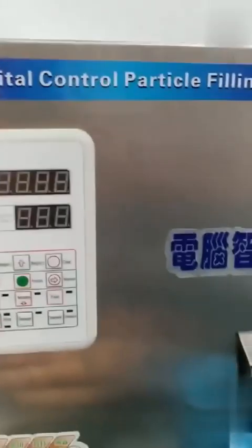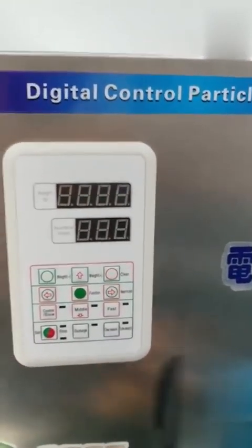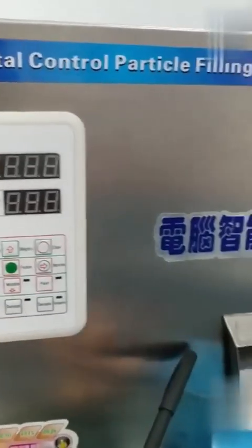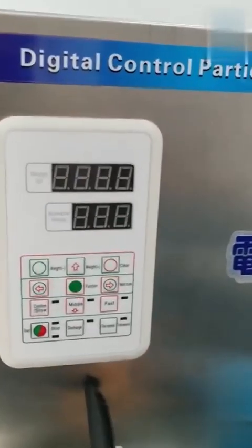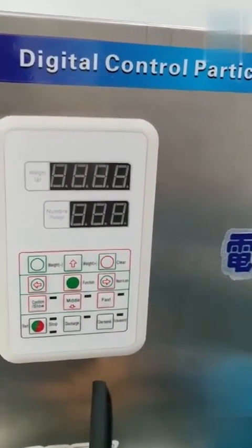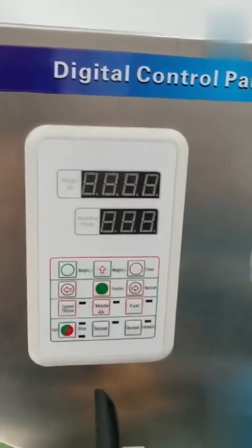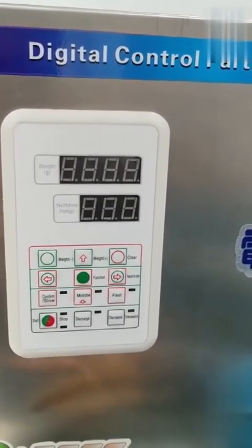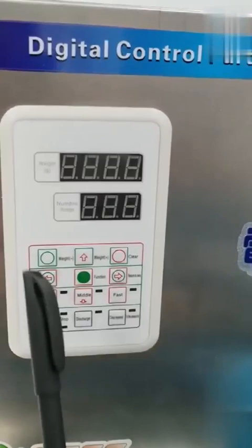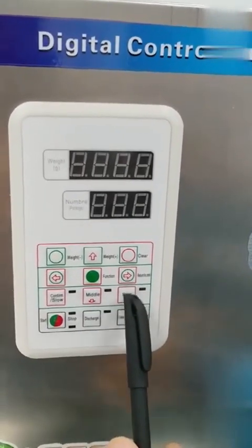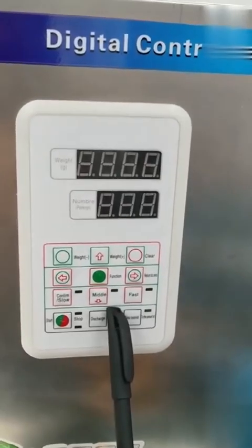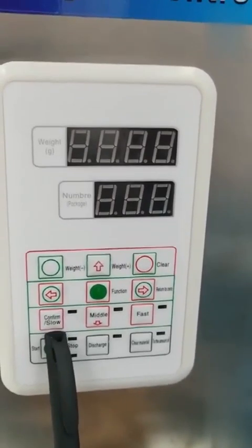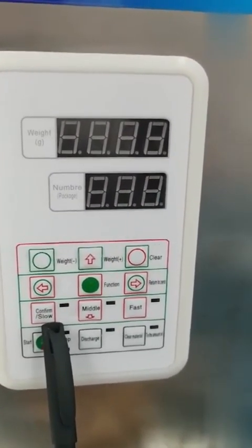How to adjust the speed for our dispensing machine. Every client is using this machine for filling different raw materials. Some are powders, some are particles, and maybe granular material. These materials have different proportions, so you will have to mess with the speed settings to specifically meet your speed requirement. Okay, as you can see on this control panel, it already has 3 different presets for the speed.